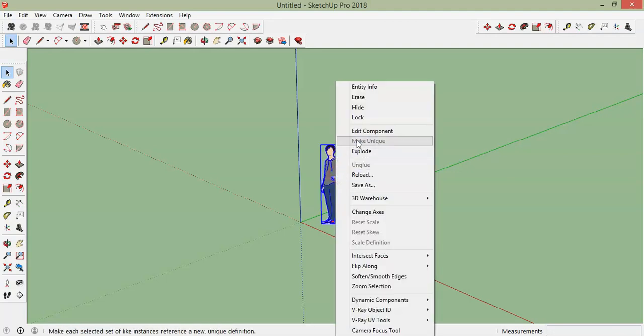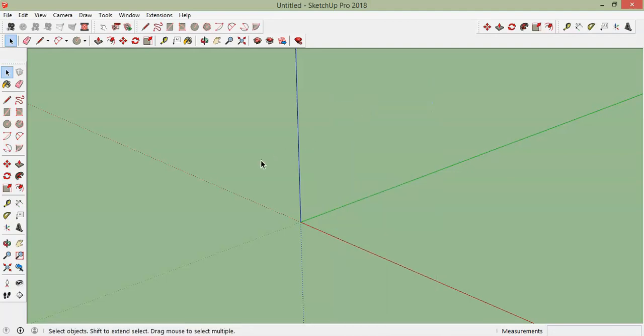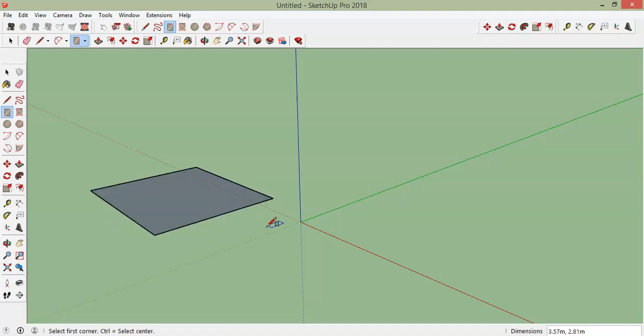Let's also hide this. Now we will start with a rectangle. Select it. In SketchUp, it is all about click and release. It's not like AutoCAD where you click and drag your cursor to draw. In this case, you can select the command, then first click on the surface, then release the cursor. Then find second point, click and release it. That's how it works for rough sketches.